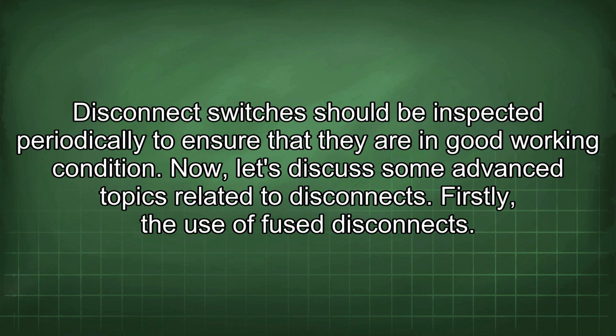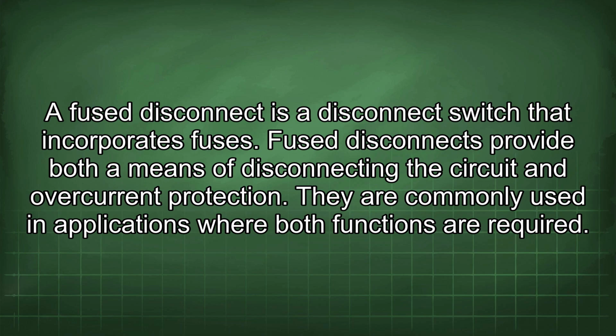Now let's discuss some advanced topics related to disconnects. Firstly, the use of fuse disconnects. A fuse disconnect is a disconnect switch that incorporates fuses. Fuse disconnects provide both a means of disconnecting the circuit and overcurrent protection. They are commonly used in applications where both functions are required.